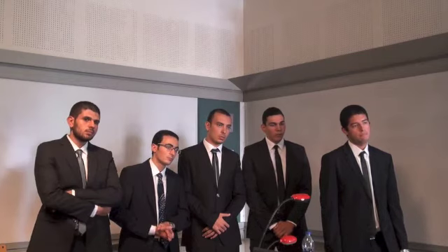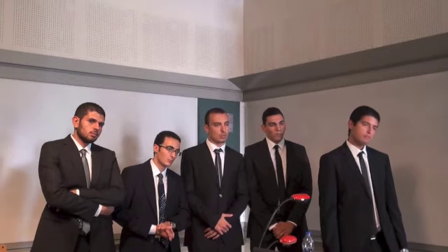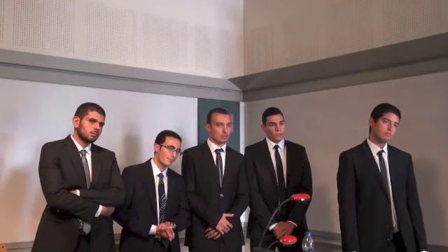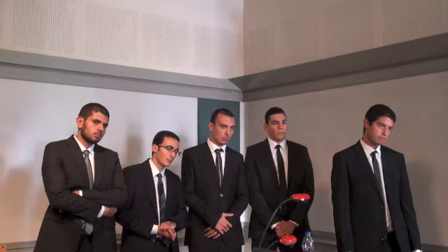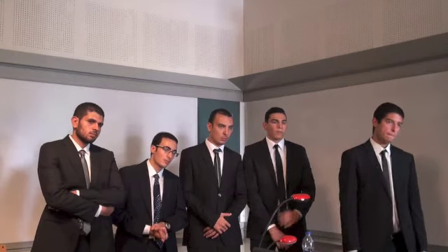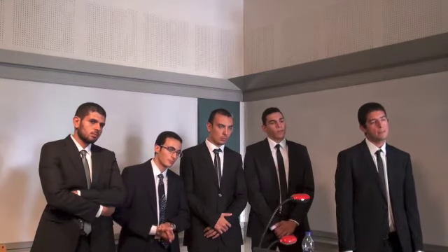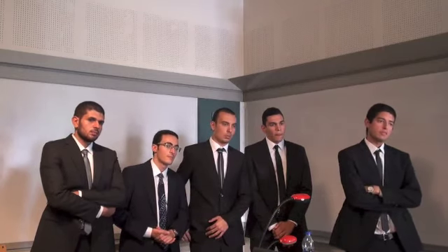This is one thing. The other thing, again discuss with your advisor: when you have it in a box, you make a box and you put the sand or whatever the underlying soil is, and you put the slab on. The confinement of the sides of the box, will that have an effect, versus in reality, where you don't have confinement for the sand that's under the slab on grade? This is something you have to consider in your test in order for your results to be really valid.